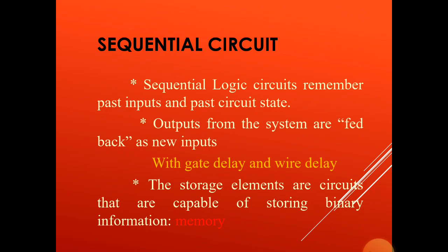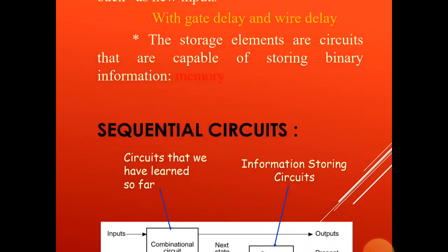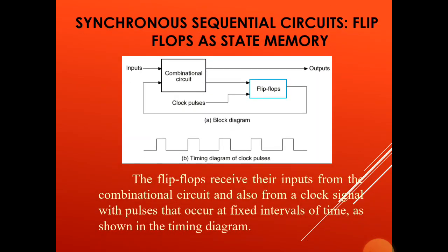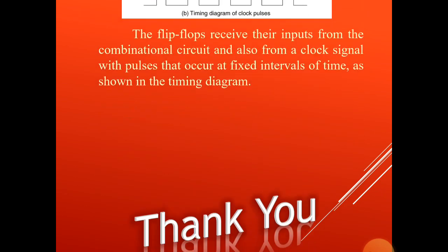Sequential logic circuits remember past inputs and past circuit states. Because of its memory, it is able to remember the previous state. So the present state and next state are considered in the case of a sequential circuit. A combinational circuit with memory is called a sequential circuit. The memory elements can be flip-flops, delay elements, clocked flip-flops, etc. If clocked flip-flops are used, that is called a synchronous sequential circuit. If unclocked circuits or delay elements are used, that is called